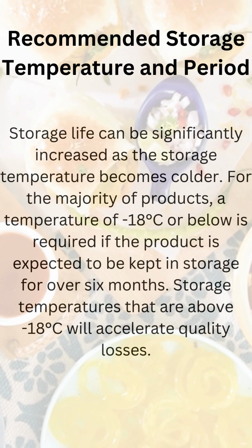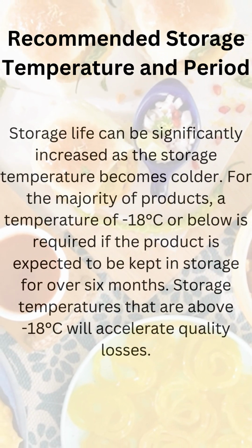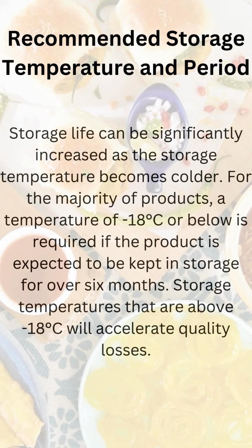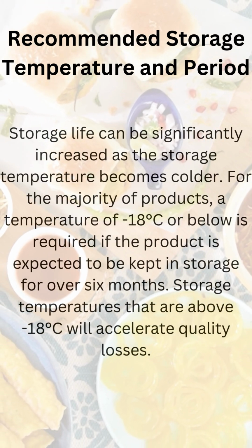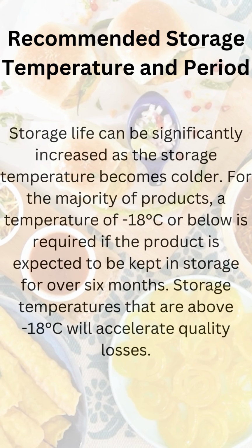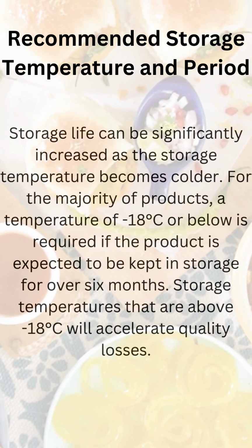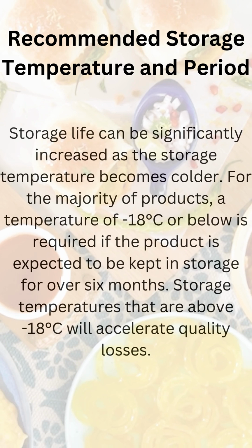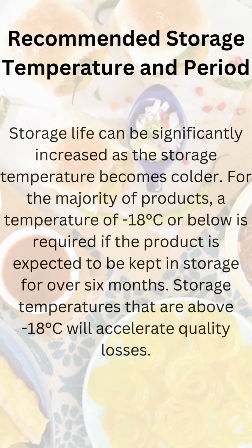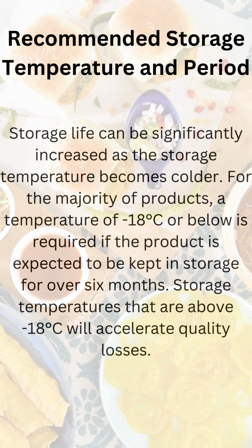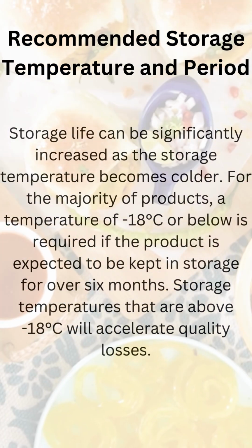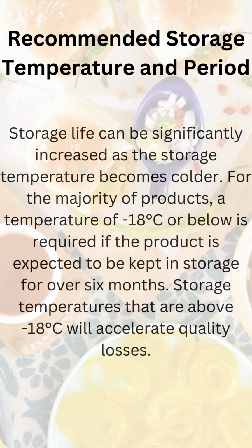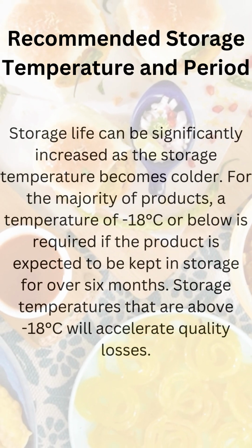Recommended storage temperature and period. Storage life can be significantly increased as the storage temperature becomes colder. For the majority of products, a temperature of -18 degrees Celsius or below is required if the product is expected to be kept in storage for over 6 months. Storage temperatures that are above -18 degrees Celsius will accelerate quality losses.